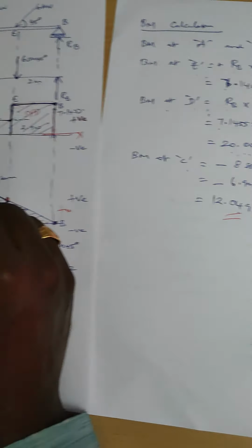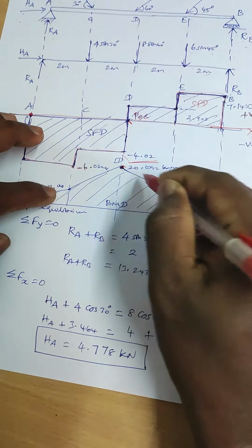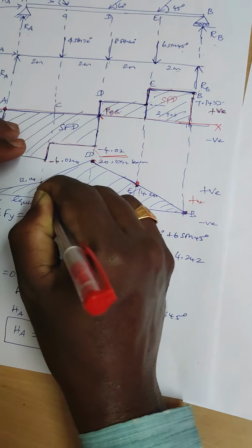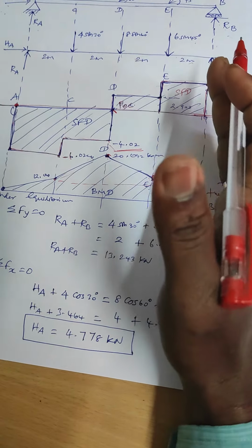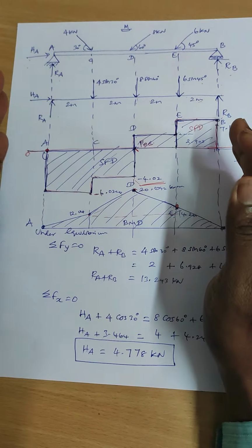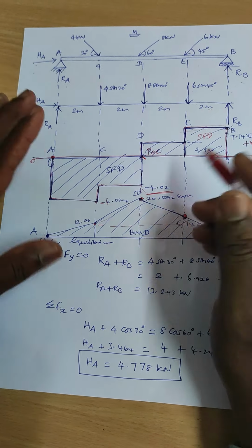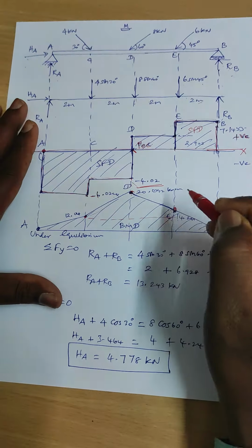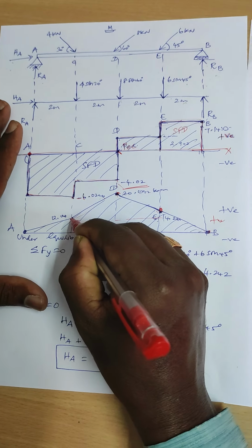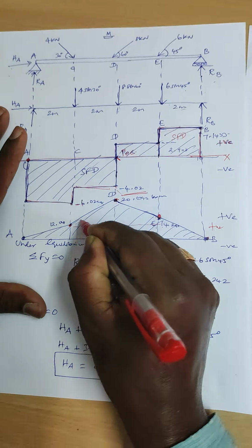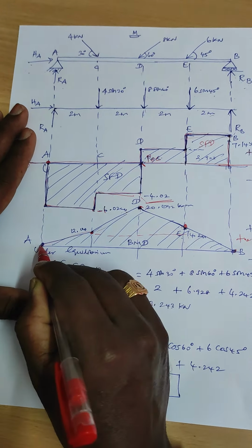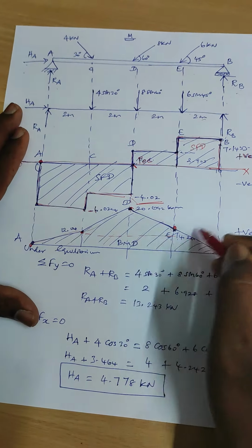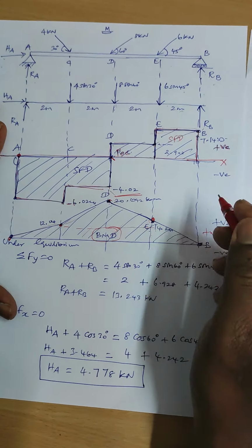After that, the bending moment at C, the value is 12.049. It reduces again from 20 to 14. Below the 14, you are getting 12. Like that, you draw the diagram. If it is on graph sheet, the diagram will be very perfect. Now we are manually drawing on plain white paper, so accordingly we draw the diagram as per the ratio. Now you draw the line here. Here it is a flat line. Here also draw an inclined line. After that, at A, the bending moment value will be 0. Draw a tapered line. Then draw the hatching line. This shape is called the bending moment diagram.